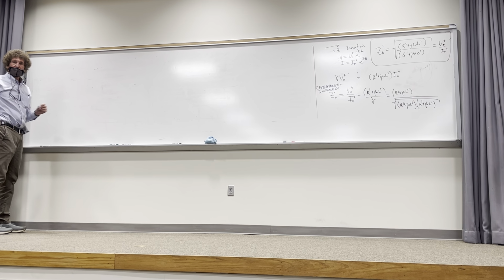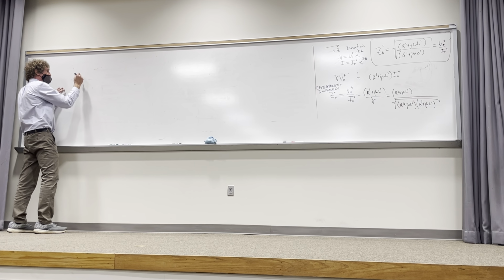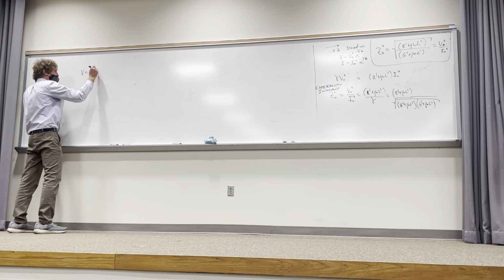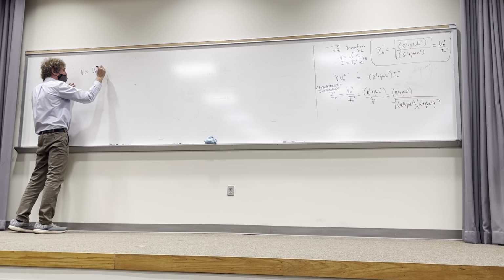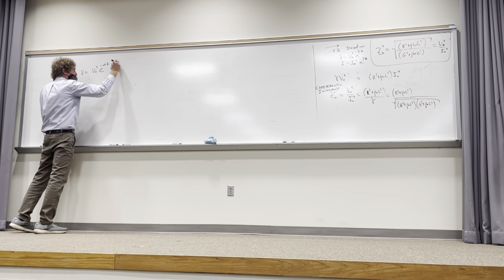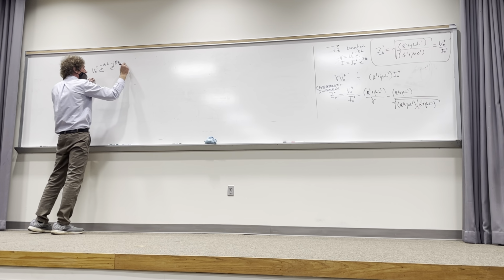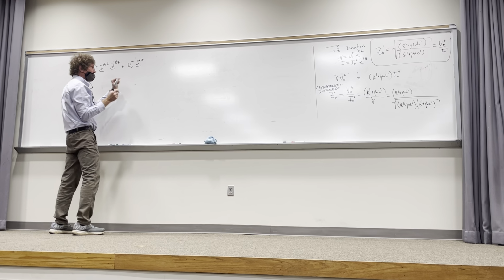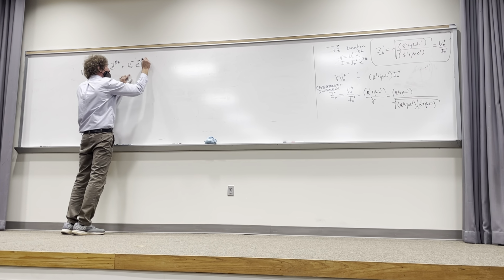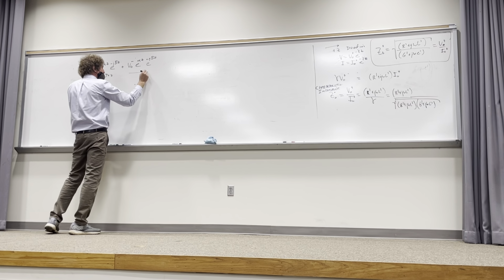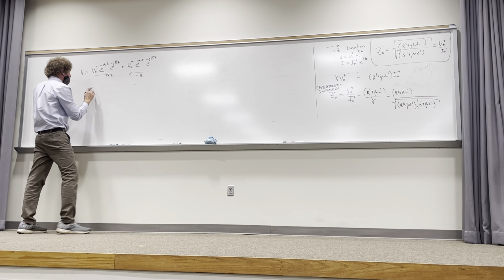Okay. When I take a look at this, this is something I want you to remember. Normally V is some V0 plus e to the minus gamma z, e to the minus j beta z, and V0 minus e to the gamma z, if there is a negative traveling wave, times e to the plus j beta z. And again, this is positive traveling, positive z, this is minus z.